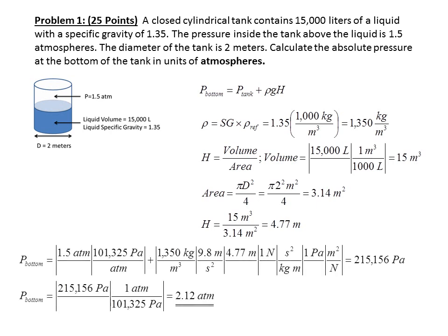Calculating the bottom pressure, we find it convenient to use units of pascals. So we'll convert the pressure above the fluid from 1.5 atmospheres into pascals, and then we'll add the fluid pressure, which is just rho GH, converting our units of measurement into pascals from there.